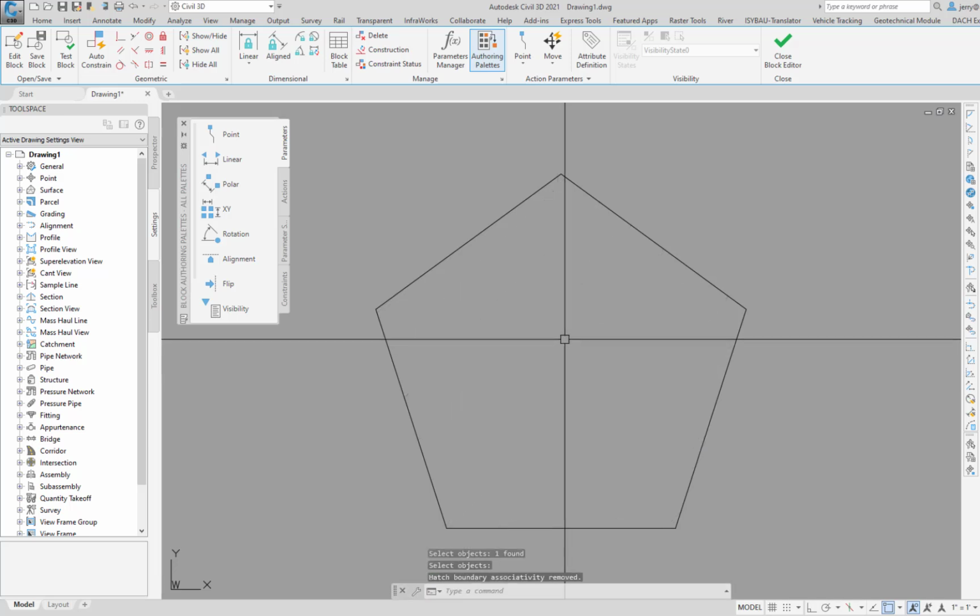Enter. When originally created, the size of the pentagon was arbitrarily set with the length of one side being 72.6543. It is generally desirable to have blocks created at a scale of 1 or other desired scale so that when inserted into a drawing, the block may be scaled as desired. The ratio of the side length to 100 is 1.3764. Scale the pentagon so that the length of one side is 100.